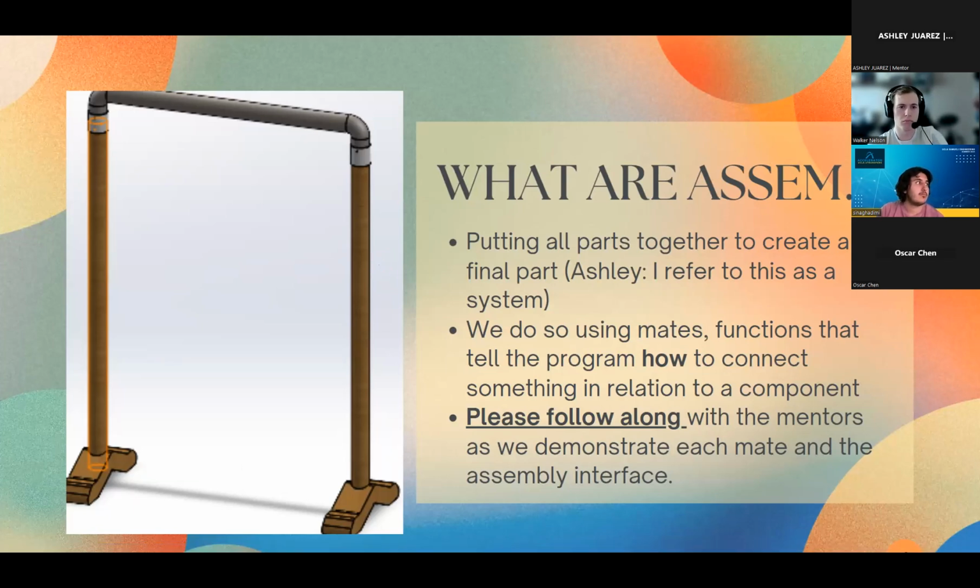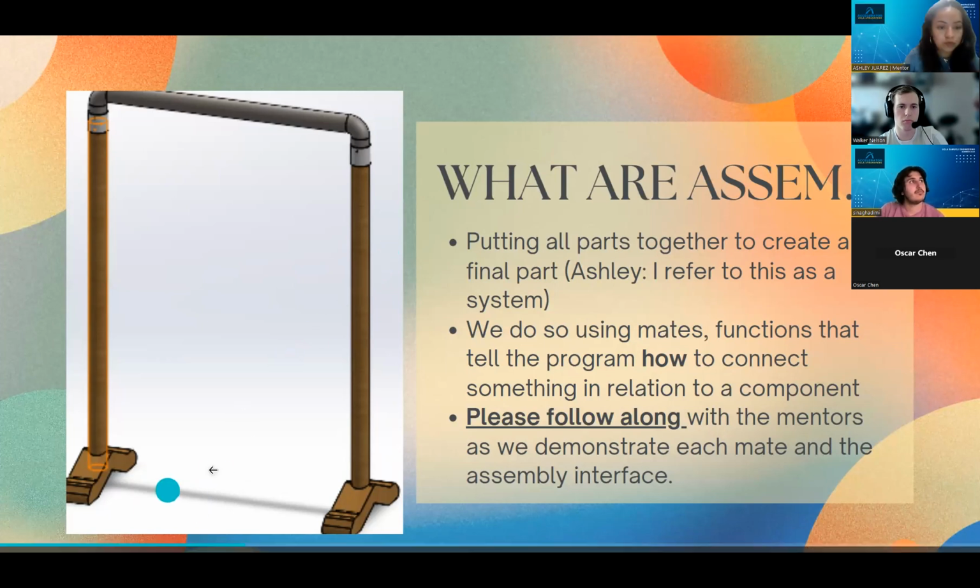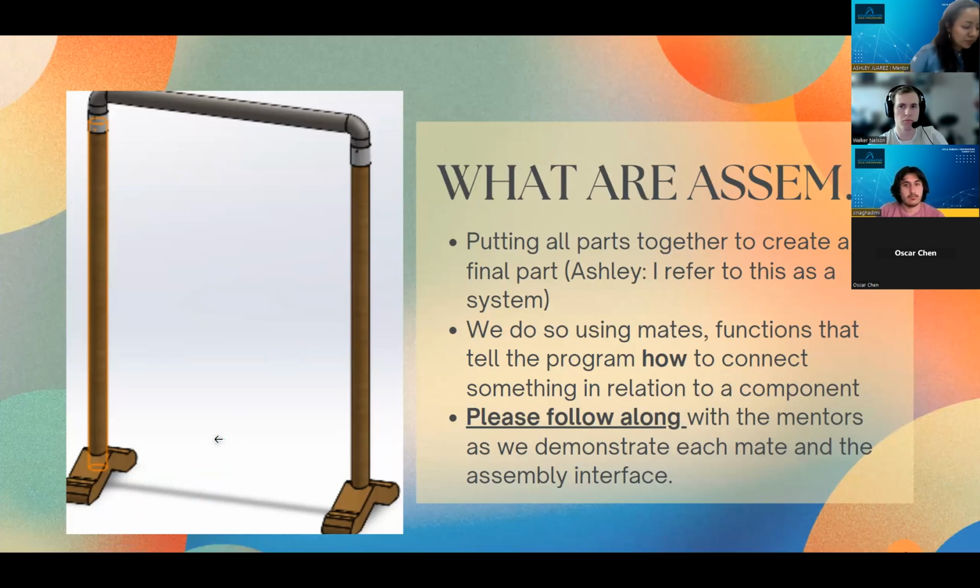I have one random question. Is there a mirror command for 3D bodies in SolidWorks? There is. I don't think we touched on that a lot last time, just for about five minutes. When you select the mirror plane first, that's the first thing it asks for. I typically orient my parts and sketches according to the planes for that very reason, because I want to have accessible all the possible options that SolidWorks has to offer.